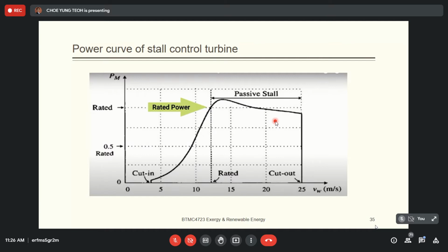But how to choose? In a location where the wind speed changes very fast, you can consider using pitch control. But for a location where the wind speed is quite constant, maybe stall control is good enough. Of course, you have to list out, for maybe 20 years, how much the power output is and what the revenue is for both, and then the net profit, because the cost is already different, and the maintenance cost for the hydraulic system will definitely be more expensive. We won't say which one is better, but both have their advantages and disadvantages. It depends on what kind of requirement you need.